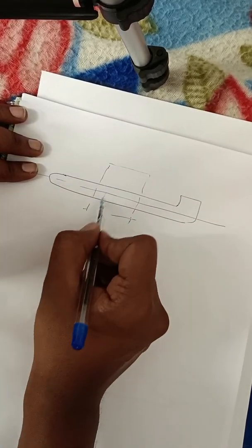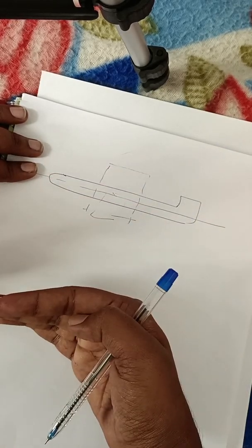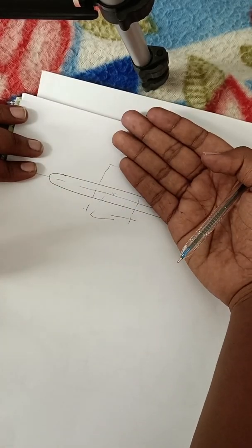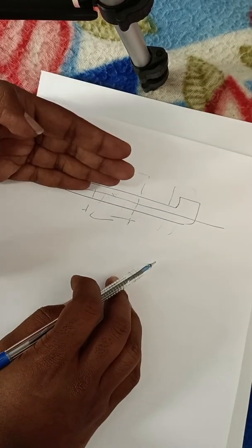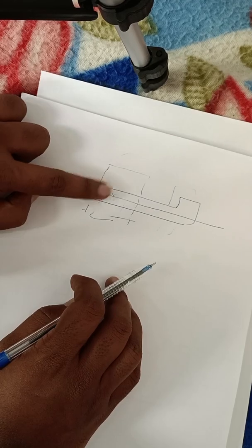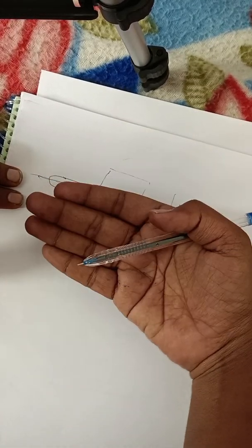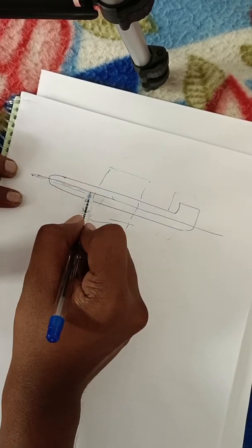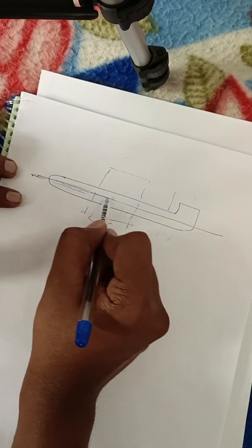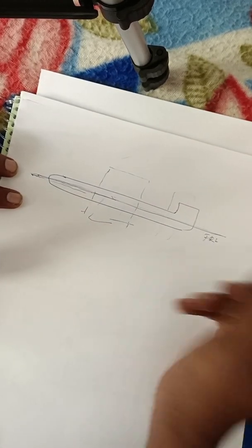This side gets one wing, that side also gets one wing, and the same amount of fuselage section on this side and that side. The entire aircraft becomes symmetric across this plane. That is the mid of the aircraft, or mid of the fuselage. So the fuselage reference line is a straight line that passes through the mid of the fuselage.